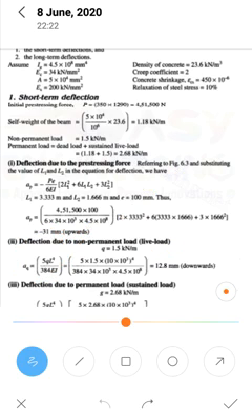So insert the value of Q as 1.5, next L as 10 meter. E and I values are both given here. After substituting the values, the deflection due to the non-permanent load, the live load, you got 12.8 mm, the downward deflection.